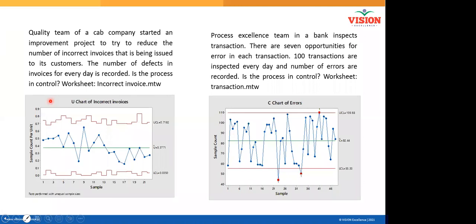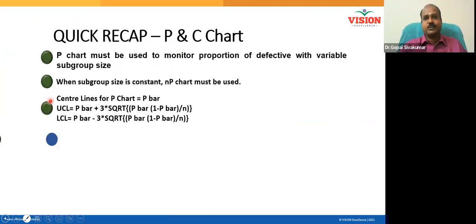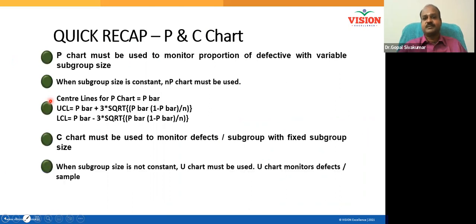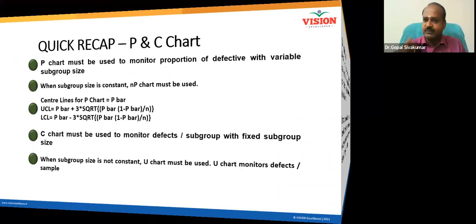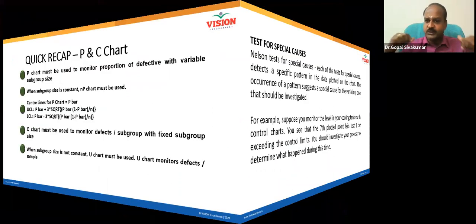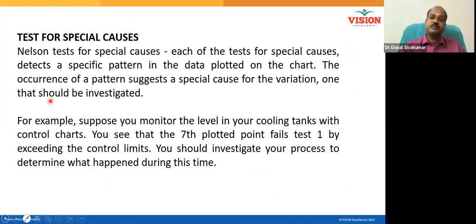That's all. Now all of you are a master in what you call statistical process control. Right? These are the formulas. Now, how to read the control chart? What have I taught you so far? If a point goes outside the control limit, the process is out of control.